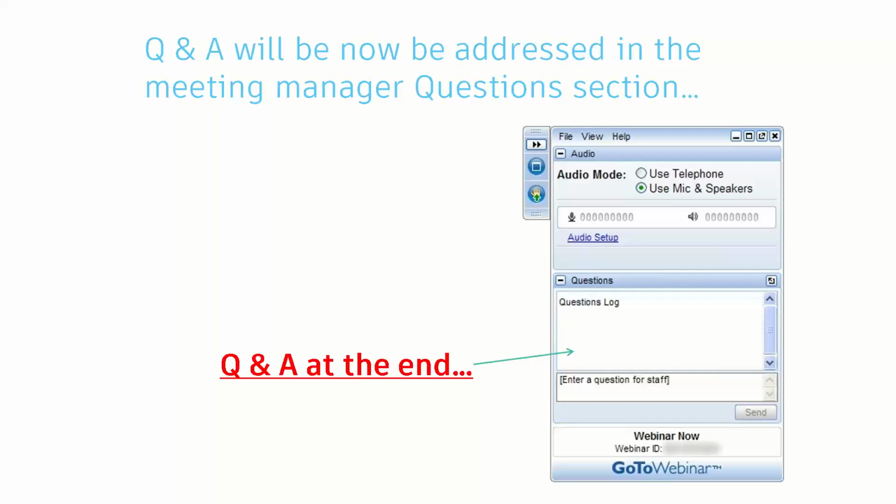We are able to take some surface models and convert them into solids and pull them into the sheet metal engine to flatten using the sheet metal rules. There are limitations because of the sheet metal type of workflow. Inventor's not intended to take, you know, a rolled up ball of cloth, if you will, and flatten it out.